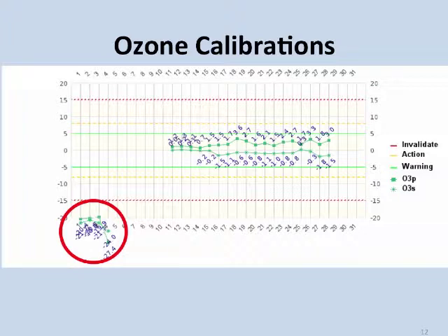Check the machine. So let's say you go out there and you check the flow, everything's looking good. You've got no faults coming up on the analyzer. Then what are you going to do? Run a manual cal? Leak check? Speaking from experience, I would say make sure you hook the probe line back up to the inlet line. Yes, that'll do it. That'll get your control chart looking like that. All very good responses here.